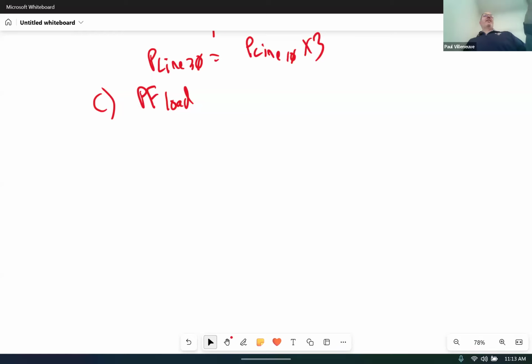But the idea, right? A power factor, it's very important to know if it's leading or lagging, right? Because if I tell you if something has a 0.9 power factor, this is the load, is that enough to be able to do any calculations on it? No, you got to know if it's got a lagging angle or a leading angle. If I told you it was capacitive and resistive, that's essentially telling you it's a lagging or leading power factor. But from what I remember, when we were grading your test, I don't remember if you said it was inductive. And had you said it was an inductive load, I would have probably given you 10 points. I might have given you a hard time saying, why don't you just say lagging? It's easier to say that, but I don't remember seeing that on your test.